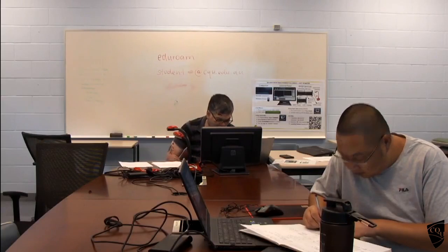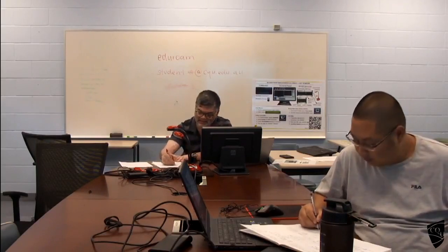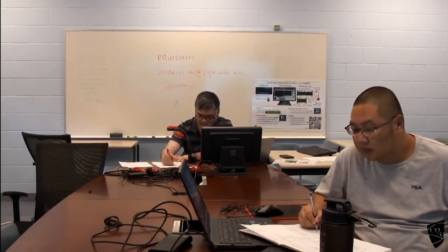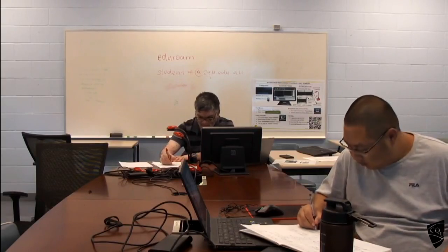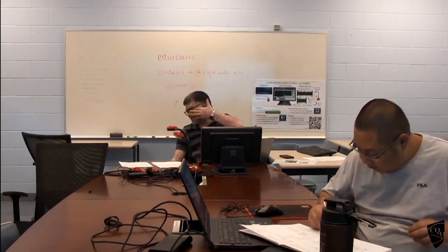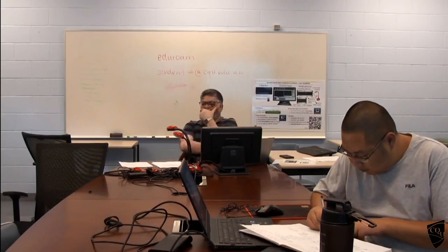So this is given in the standard. It cannot exceed I effective maximum, that is given. So look at this. This is the cracked section. This is uncracked. So we need both I's to get the effective I value. Okay.